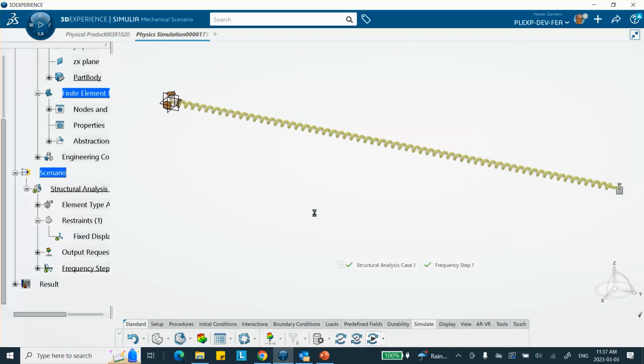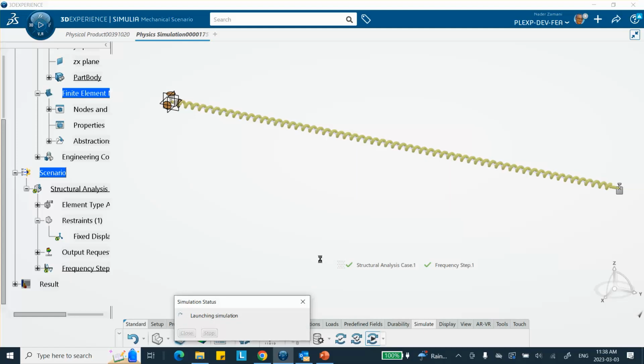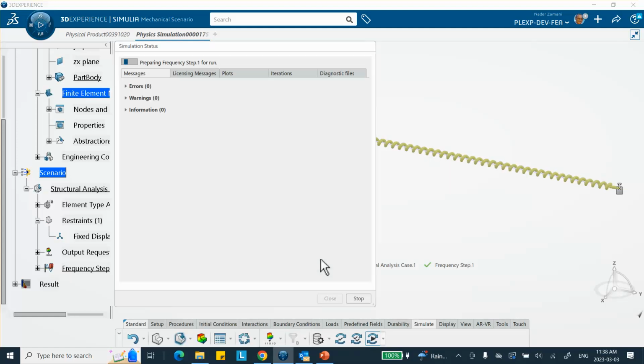I suspect you're going to get that natural frequency 0.225 hertz, and I'm pretty sure you will. There will be two rigid body modes too, which is basically motion in probably X and Z direction, but 0.225 is what I'm looking for.